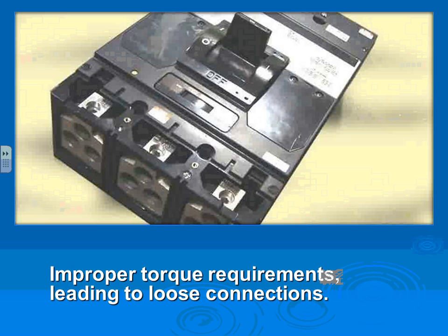So when it comes to circuit breakers, guys, probably a lot of things: loose connection, over torquing or under torquing. The lugs on a circuit breaker are a common mistake that can lead to arcing and sparking. So the circuit breaker that's supposed to be your valve for protection becomes a source of hazard by over or under torquing or not properly maintaining the torque on these circuit breakers.